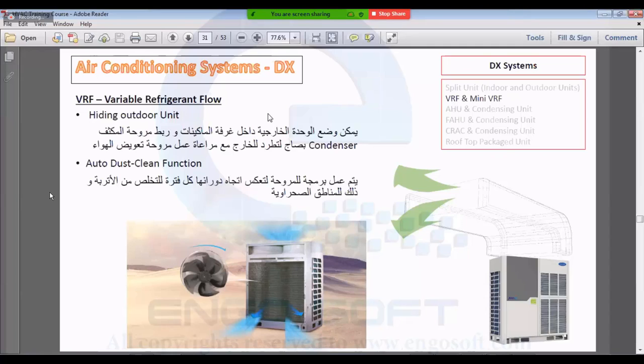You know ventilation, right? So you have to provide ventilation to this unit if you put it inside a mechanical room, so it can be cooled efficiently. And it has to exhaust the heat from the unit, right? So you should mount a duct in the unit to the outside of the building.